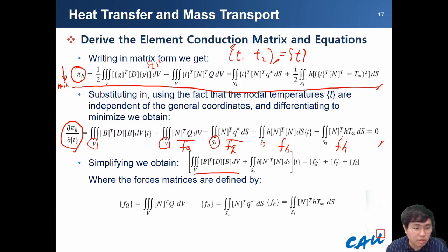It is because the convection component has some unknown variable T here, so we cannot say that this is a boundary condition, although the form is like that. This part can be defined only on specific boundary surfaces. However, these two terms are in our governing equation, and the others are just the force terms.